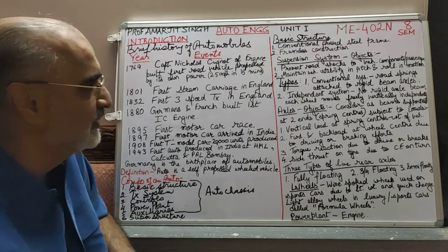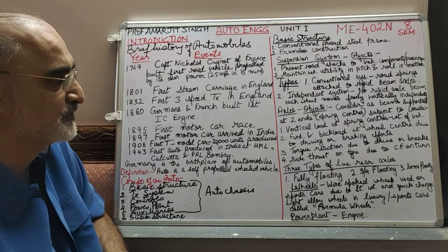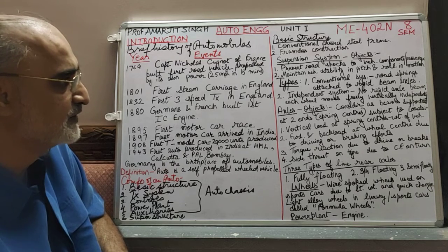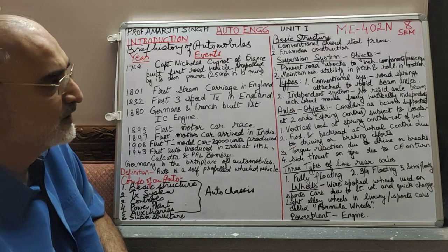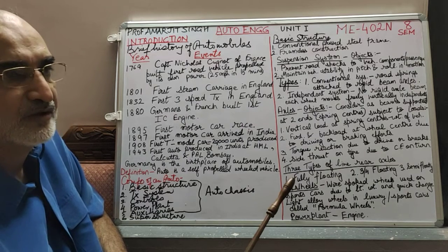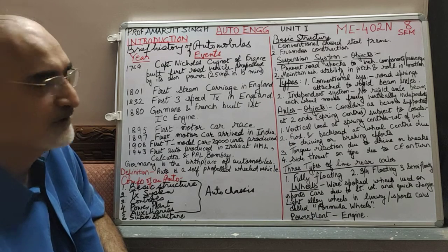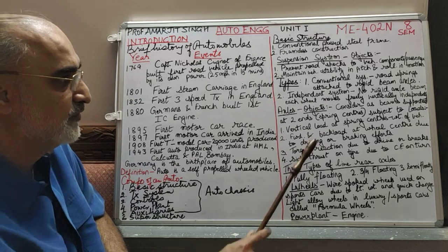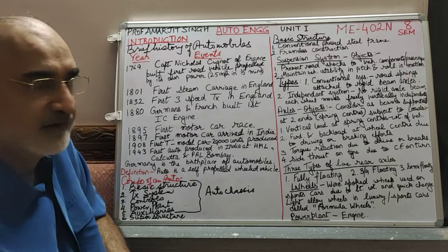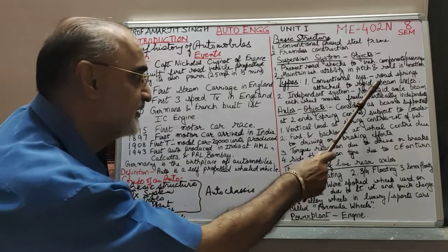First is the conventional system, where the road springs, you must have all seen on the side, are attached to the rigid beam axles by means of two U-bolts and tightened from below with a nut. So, the road springs are integral with the beam axles. This needs to be noted.